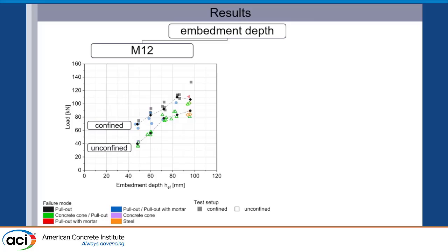I forgot to mention before, for all the tests with 8D, the steel elements were hardened in order to avoid steel failure. However, that was not possible because the concrete strength was also very high. Similar results we see for unconfined. In this case, up to 6D we have a very large increase of the failure load, and from 6D to 8D we have an increase, whereas for the confined we saw that from 7D to 8D there was no increase.